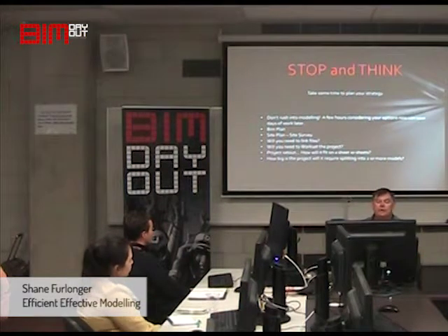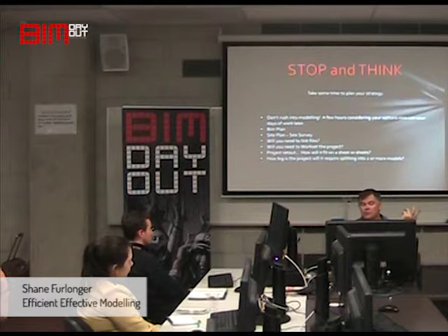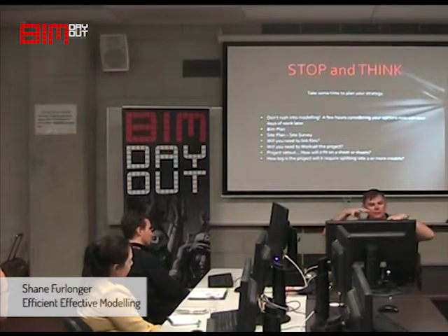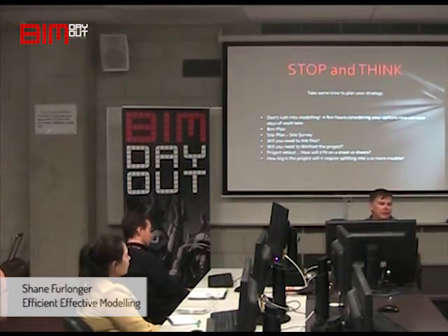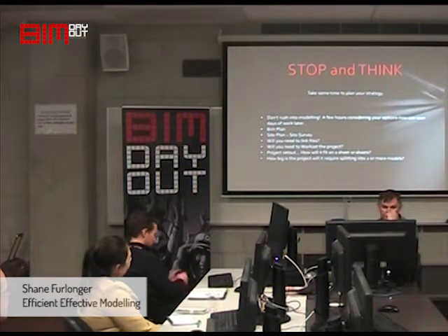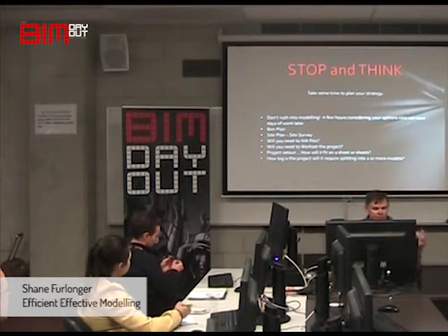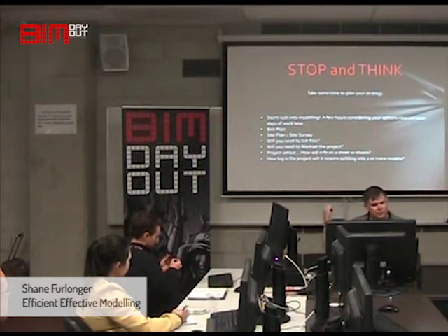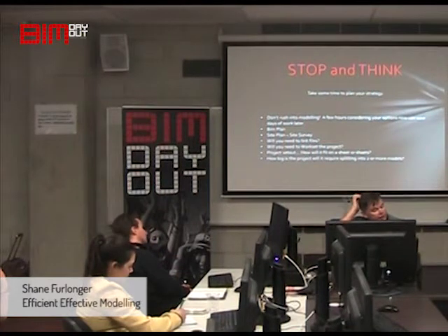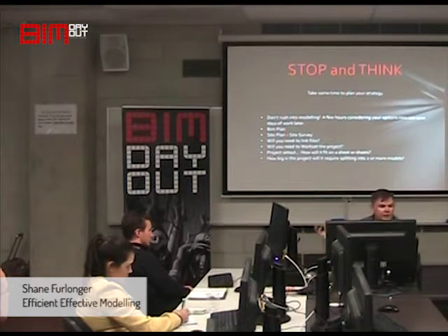And then, will the building require splitting into 2 or more models itself? It may be a huge tower, like 140 William Street. There's lots of various bits and pieces going everywhere. That could easily be split up into a couple of different parts. Some people like to split the facades and the shell from the core, from the main structure of the building, depending on how you're doing things. The hospital that's just being done by Hassell in Midland has been split up with a shell and core and a facade.